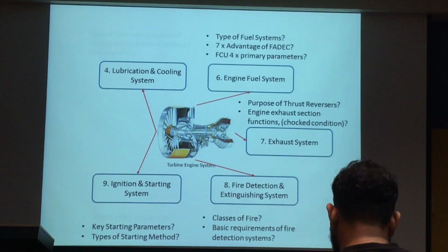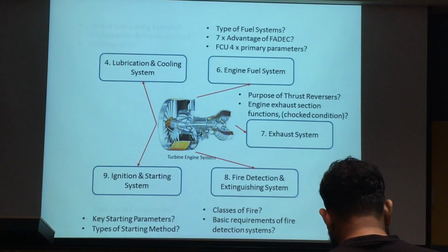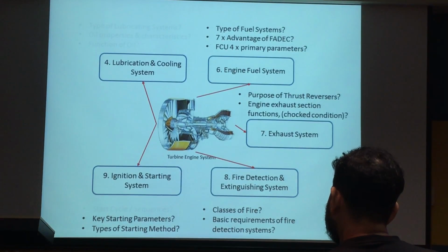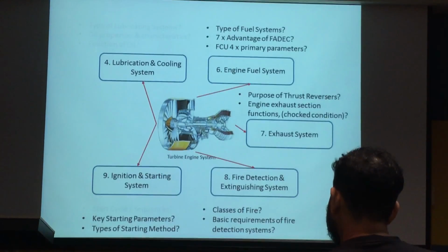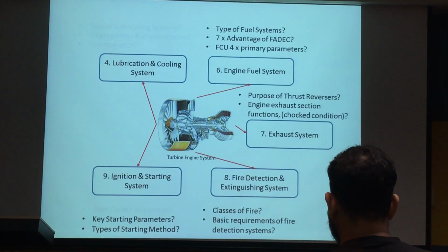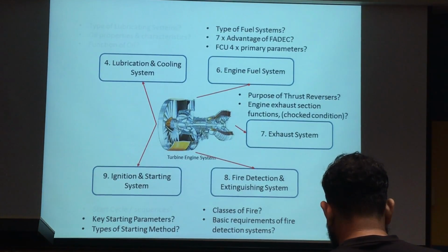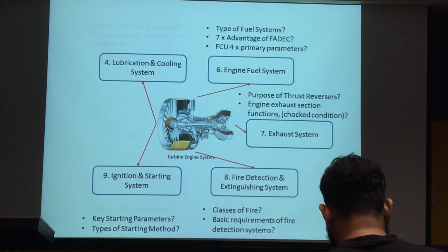For turbo jet engine, can only apply what kind of reverse thrust? Listen here. For normal jet engine, your F-16, F-15, or the military aircraft, they're using the turbine shell, correct? It's only a turbine reverse, or gas reverse, or hot stream reverse, because they don't have fan stream. Clear? Only turbo fan got fan stream. Then you can have cold stream reverse plus your gas reverse. They can apply both or apply either one. All clear?